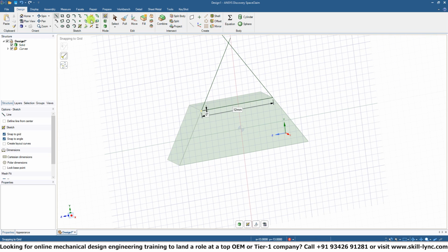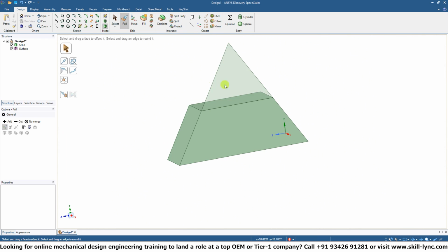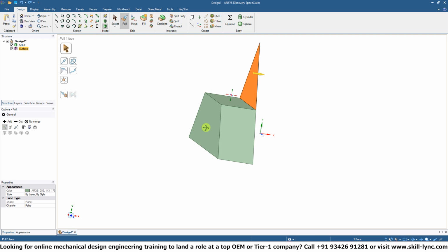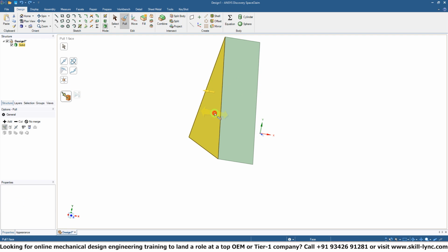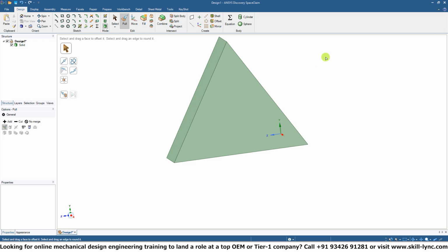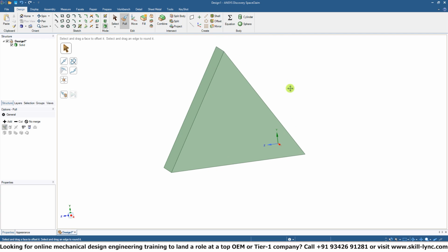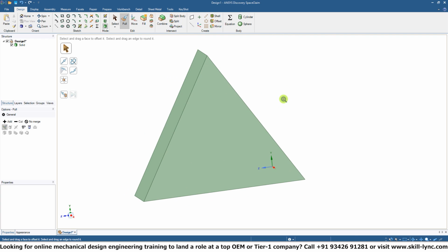Now that we have completed this sketch, we can trim the unnecessary entities. We can go into Pull and we can autocomplete the surface. Actually, if we select this surface and we select Pull to this surface, it will autocomplete it for us. However, you can see how that would get really tedious and it adds a lot of extra steps and takes quite a bit of time.